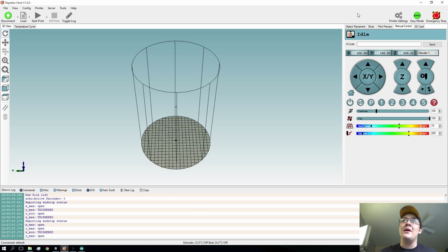So like I said, if you hit home and everything went up, everything's good. If they started to go in a down direction, you need to invert the motor information. That's probably the only thing that should cause that. If one axis is not moving or something like that, it's probably a wiring problem. Probably something isn't hooked up correctly. If you've killed the motors, it might move. So if you've killed the motors, home again.